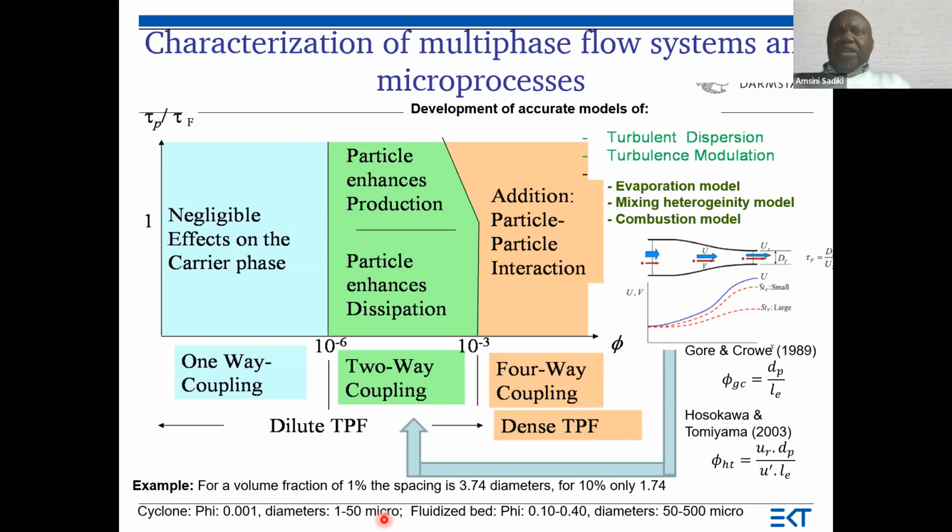This corresponds to a diameter in this range. We obtain this very simply if we use the formula we had. L divided by D is approximately equal to 10 if we say that the particles are isolated. We have a fluidized bed, so this quantity ranges between these two values, so that the diameters cannot be outside this interval.